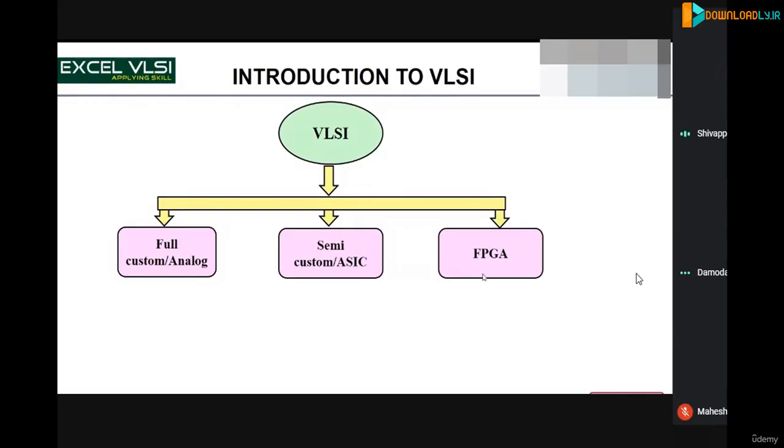Basically, in order to realize the hardware design, we use languages and tools. The languages are HDLs for designing, that is Verilog or VHDL. For verification, we use other languages. Basic languages like Verilog and VHDL you can use, but for advanced verification you have to go for SystemVerilog and the UVM methodology. And even higher level languages like C can be used for system level verification. Okay, and the other part is tools.